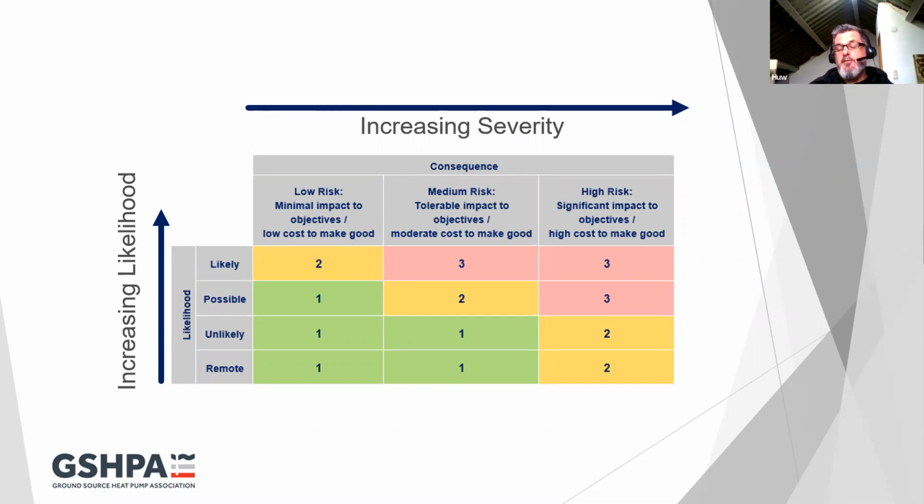Let's say this wetland receiving warmer or colder water from the operation of your ground source heat pump system. Well, that will be the sort of project where we would tend to want to de-risk or at least investigate the chance of that adverse impact happening.